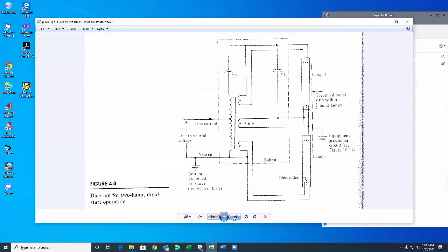Okay, so one of the inconveniences of the fluorescent lamp is the stroboscopic effect. That is 60 hertz, every 2 times per cycle. So at a frequency of 120 hertz, the current goes through zero. It crosses the zero axis. And then the lamp dampens a little bit, with less intensity. So that variation of intensity, sometimes some people can see it as stroboscopic.